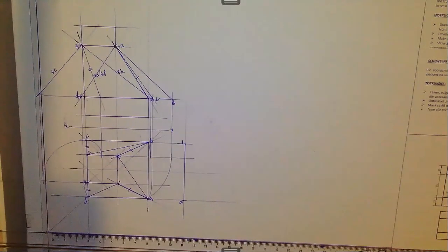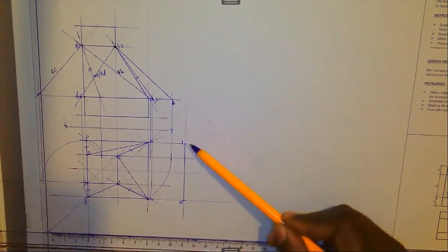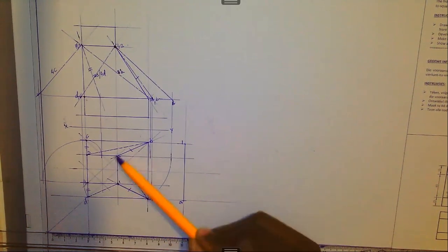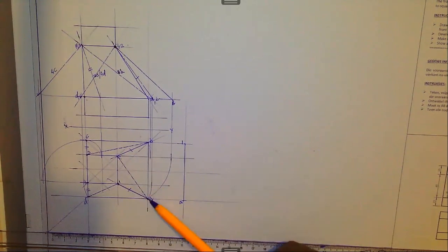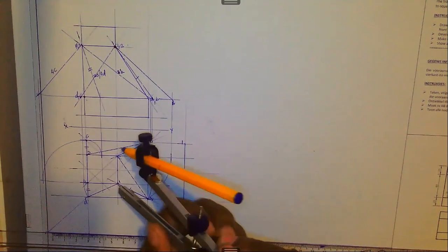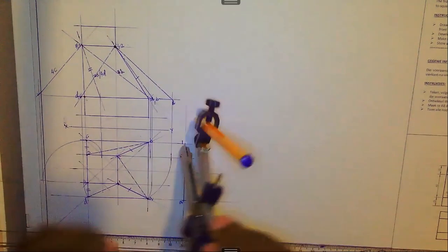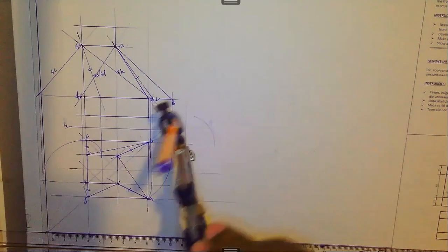Now, the next thing that I want is to find point number 2. Remember, this is a true length, so I have got two standing positions, point 1 and point A. For me to get to point 2, I need to say 1 to 2 and A to 2, okay? So you take your compass like this, and you stand at point 1, describe an arc. There you go, a faint arc like that.